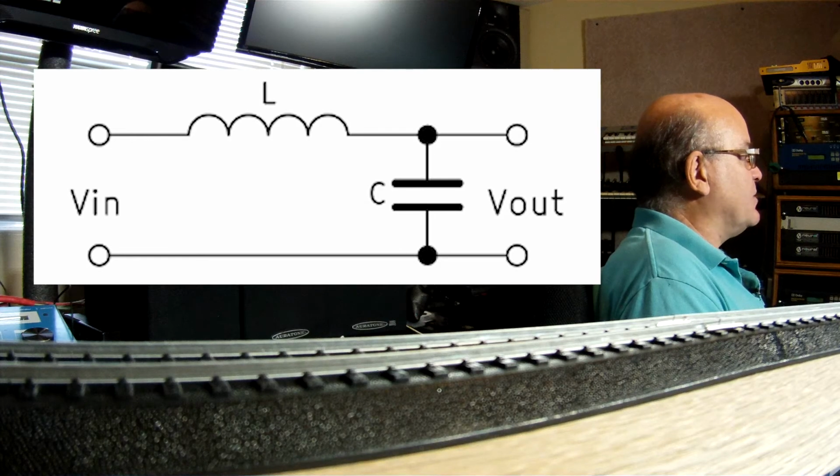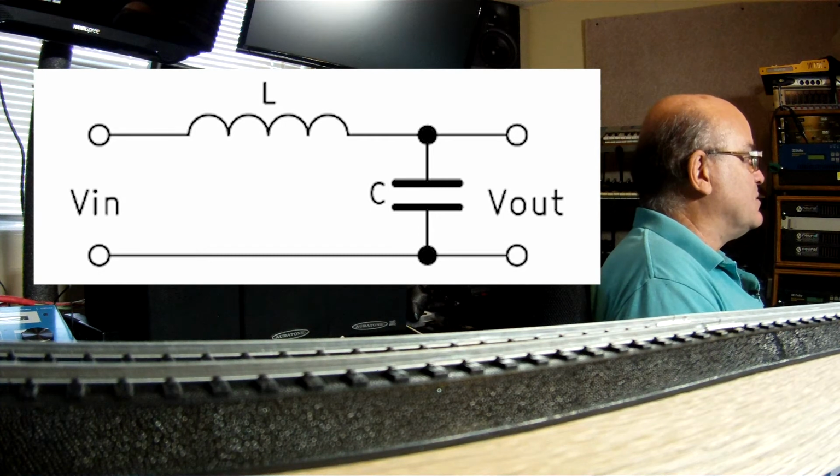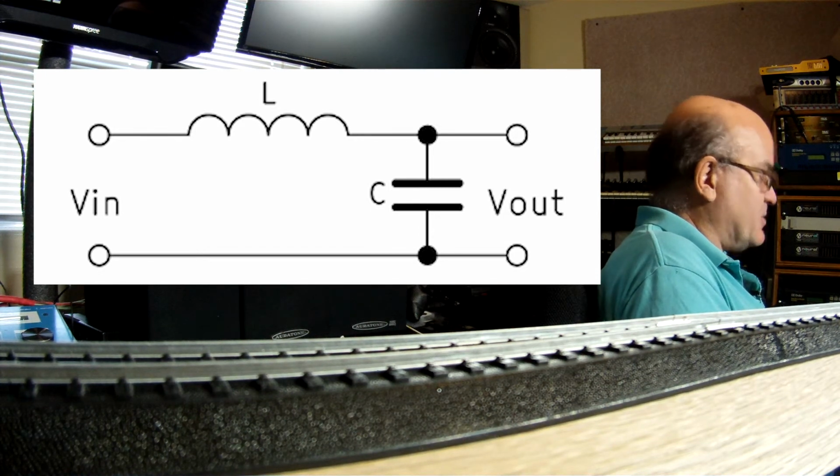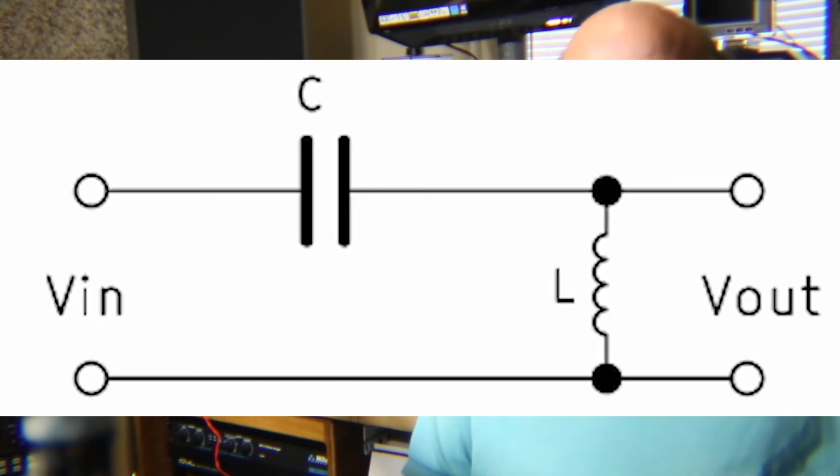The circuit used in a passive crossover is what is referred to as an LC filter. Basically, L being the symbol for an inductor based on the word loop, a loop of wire, which is the most basic inductor, and C being the symbol for capacitor. They are so simple that the low-pass part is an inductor in series with a capacitor wired in parallel, while the high-pass part is a capacitor in series with the inductor in parallel. That kind of circuit is what is referred to as a first-order filter.